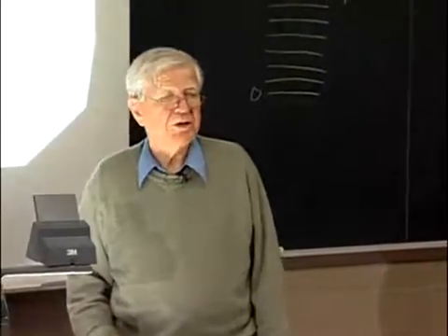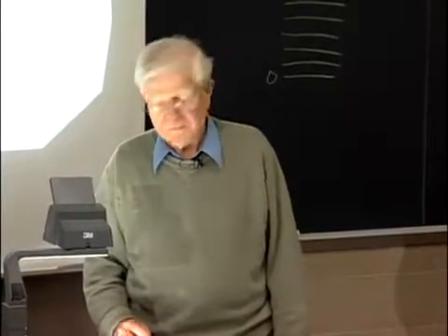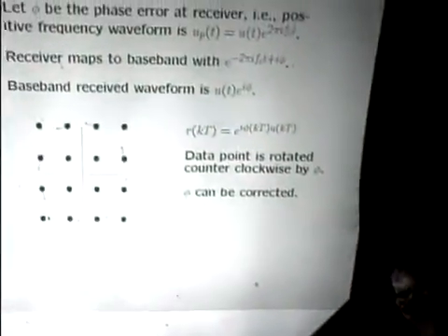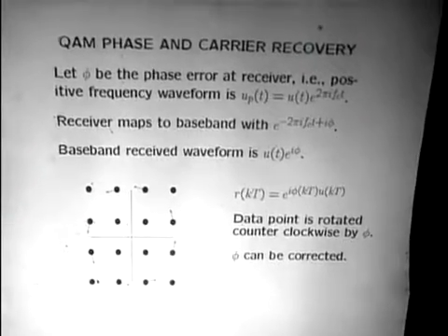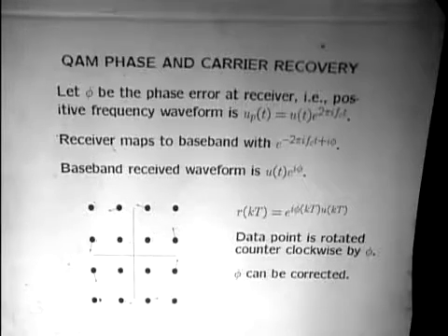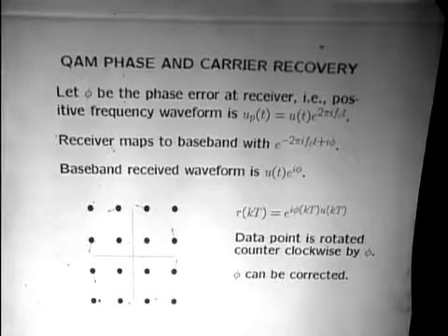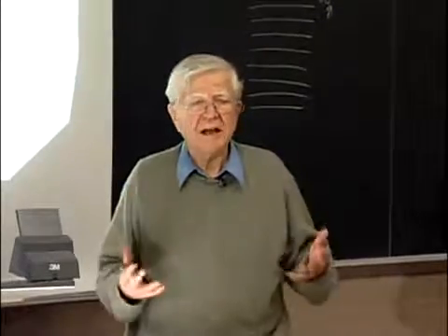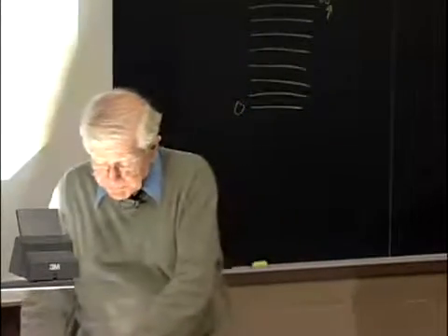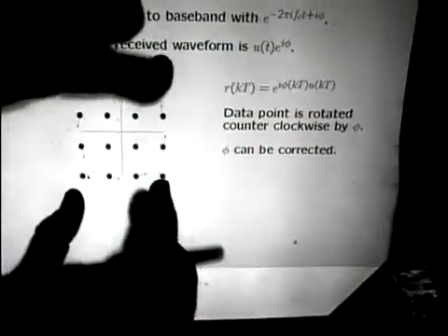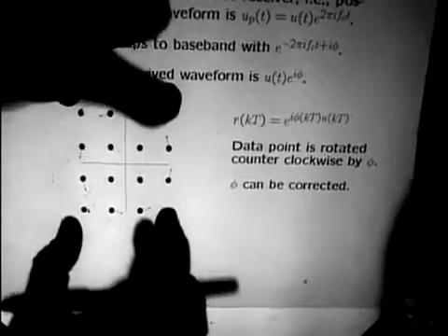What's the problem with this? You look at this diagram and you say, okay, suppose there's some huge error, or for a long period of time, things get very noisy. What's going to happen? Well, if you can't decode the data for a long period of time, suddenly these phase errors build up, the channel stops being noisy, and what could have happened is that your phase could be off by pi over 2, which means what you should be seeing is this.